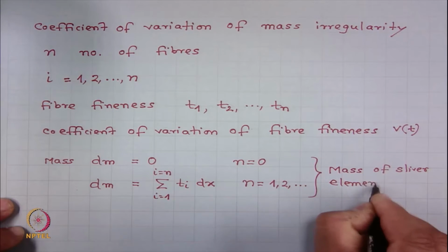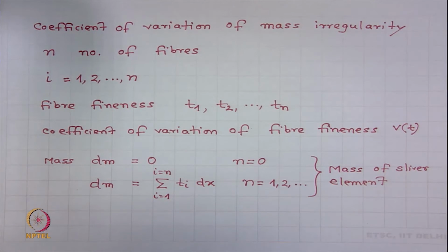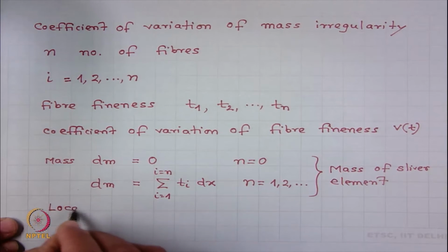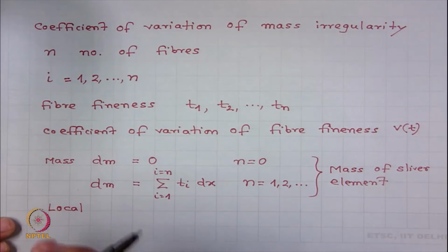Small element of sliver, right. Now, what will be the local sliver fineness? Local sliver fineness means the fineness of a small element of sliver.